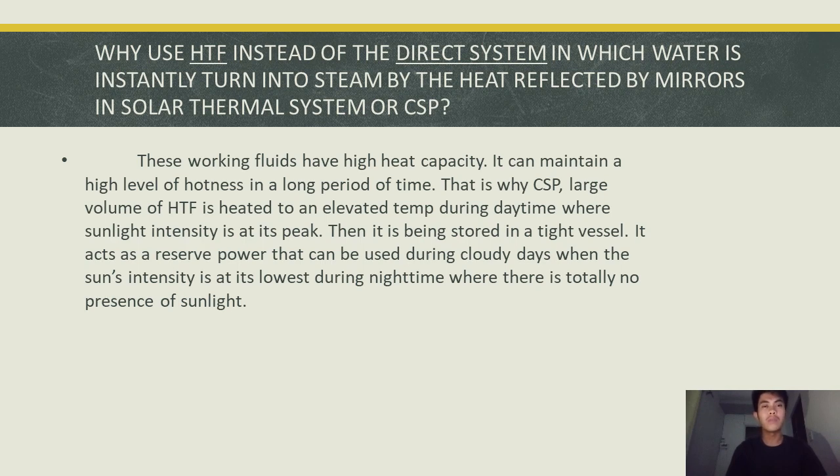Typically, a good fit between a heat transfer fluid and an application happens when the required fluid temperature of the process falls right in the middle of the operating range of the heat transfer fluid. Staying away from either extreme allows for good overall heat transfer efficiency and minimal fluid degradation. One quick rule: there is no reason to consider fluids that have a maximum bulk fluid operating temperature below the bulk heat transfer fluid temperature required by your process. Cross those fluids off your list right away.